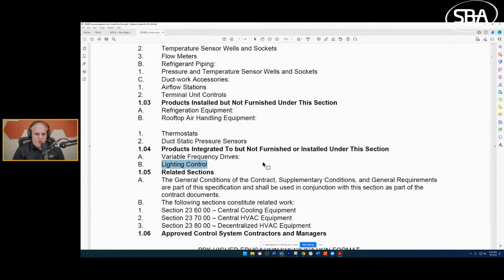And then you have what are called competing leads. That's where the building automation system schedules the lighting on, but then the lighting system schedules the lighting on, and they conflict, and you get this Christmas tree effect where the lights are on, the lights are off, they're on, they're off. You just need to be cognizant of that. Whenever I see integration to another system, I want to know who is going to be the lead system.